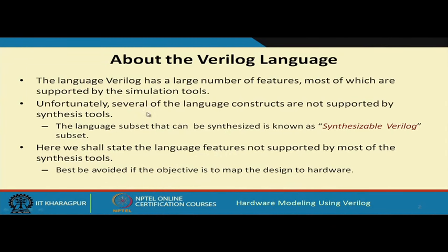But as I had said, there are some language constructs which are not accepted by the synthesis tools. The subset of the Verilog language which is actually accepted by the synthesis tools is referred to as the synthesizable Verilog subset. Now, in this lecture we shall be looking at some of the language features which are not supported and some of the recommended styles of modeling for synthesis of circuits, both combinational and sequential.